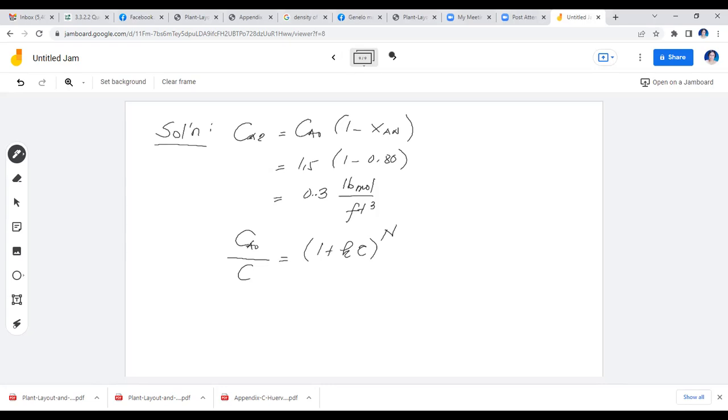that you intend to determine the concentration of. In our case, we have this specifically written as CaO over C sub 2, and we equate it to 1 plus K times the tau raised to, of course, this would be 2. If this is, let's say, a 3 series CSTR, then this should be C sub 3 and this should be 3. So this is the more generic formula, and this is the specific formula that we're going to use.